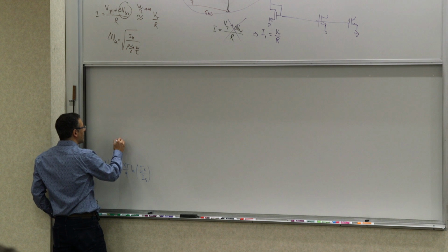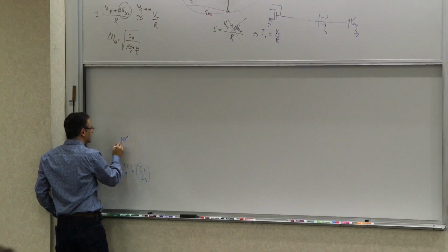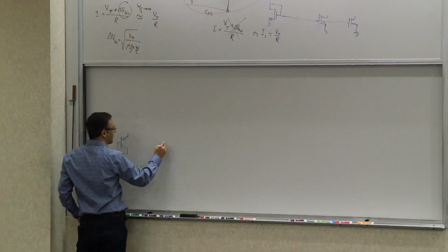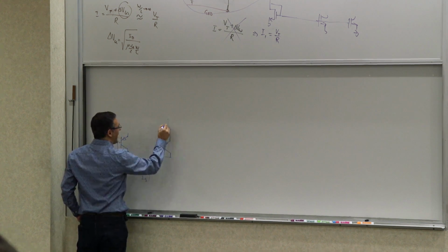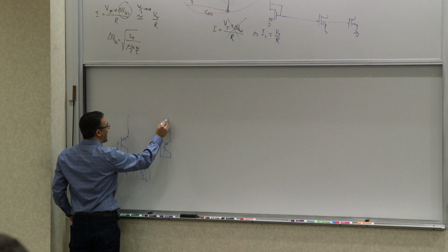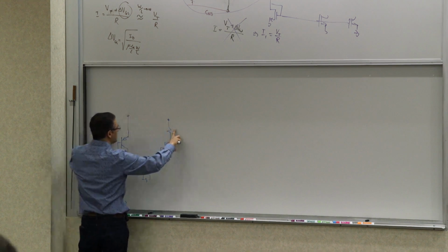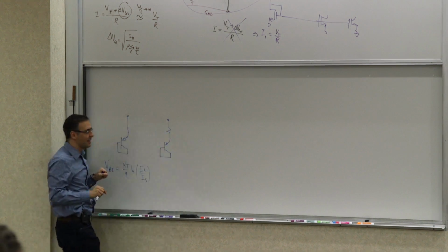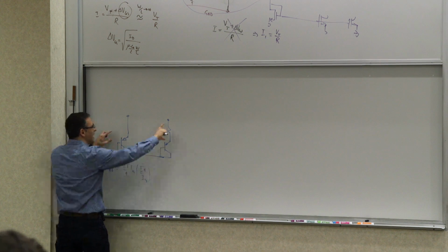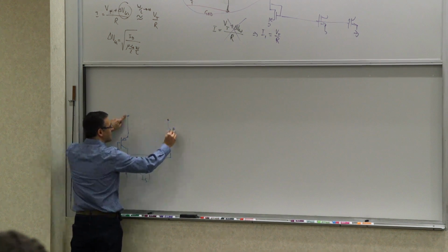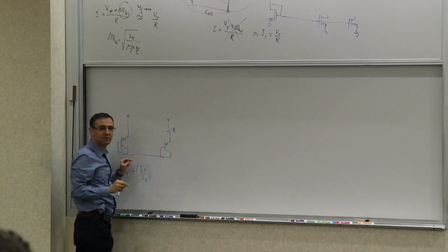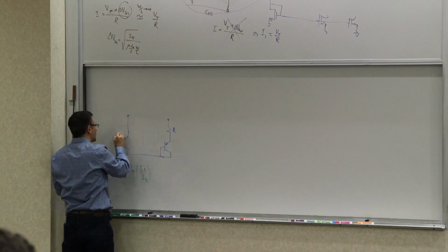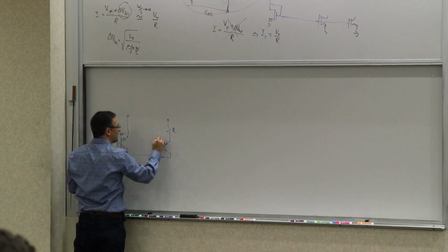What if I could take one VBE and another VBE, and let's say I subtract them from each other. In other words, I force these two voltages to be the same. If I force these two voltages to be the same, and I have a resistor here, the voltage across this resistor, do you agree, would be this VBE minus this VBE? So let's say VBE1 and VBE2.